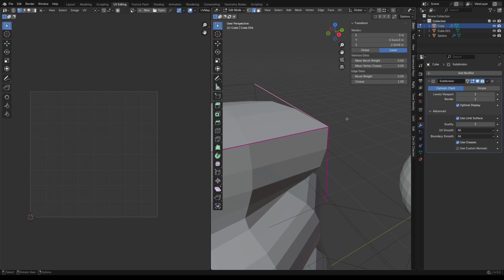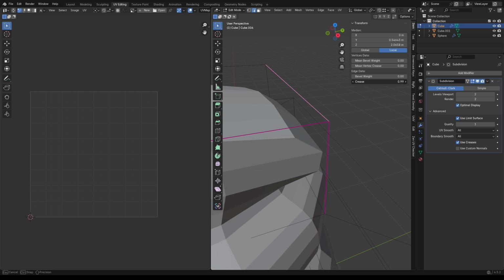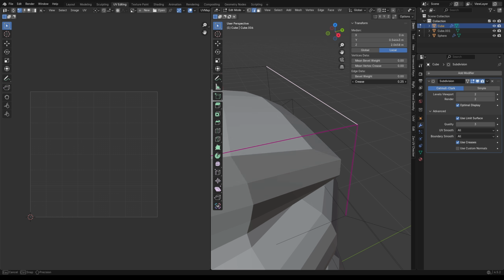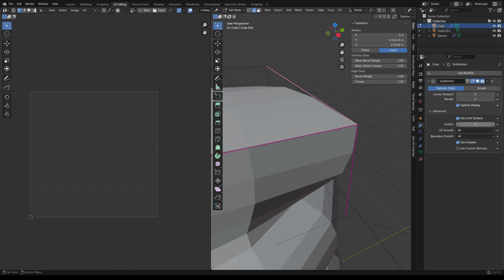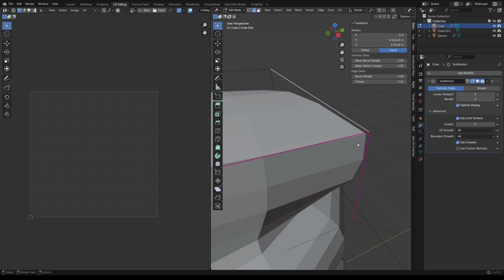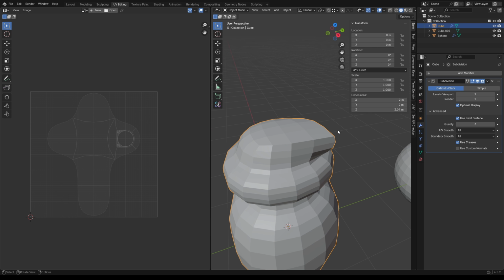Now, before I mentioned about the quality that it affects also something else, and that's the creasing. If I'm creasing this edge and its quality is on 1, if I go down, it immediately goes to the starting position or almost there. You can see that it goes there and then it jumps. So if I push the quality to 3, this distance before it jumps to the corner is different. If I put the quality up to maximum, you can see it's almost before the end, before it does the jump. So it's more accurate. It allows me to move the crease way more. So this is the quality and what it does. Creasing is very handy. I personally don't use it much, but feel free to explore and you can tell me what your experience with it is.